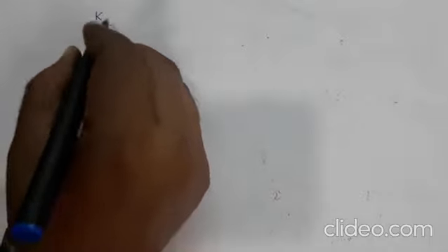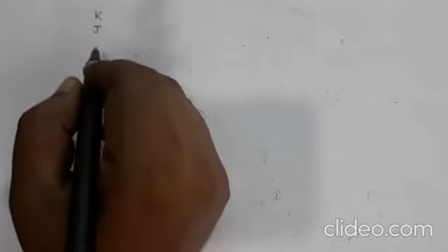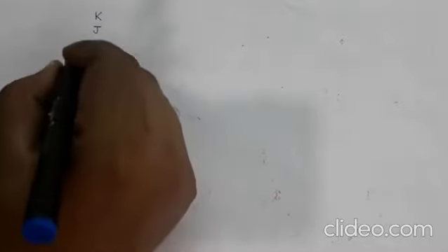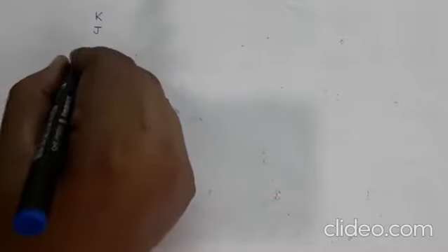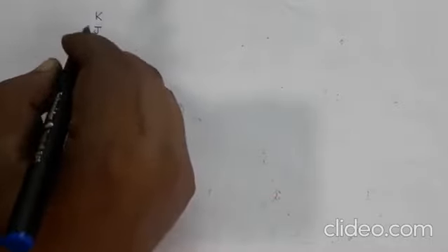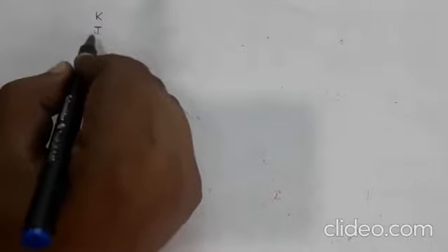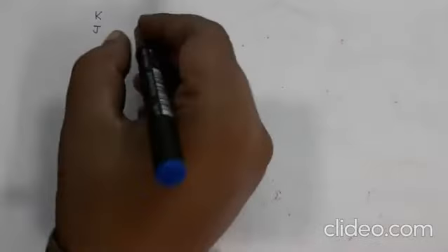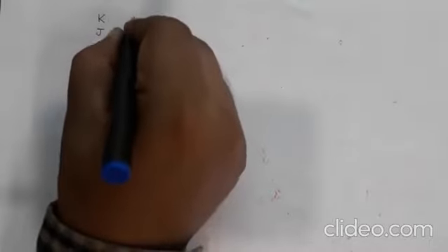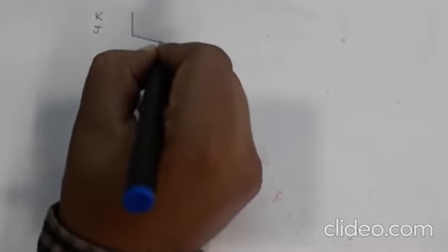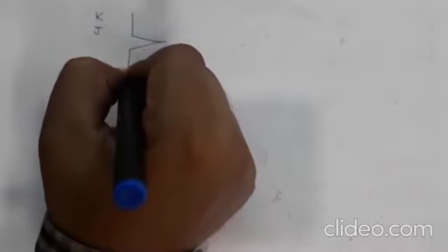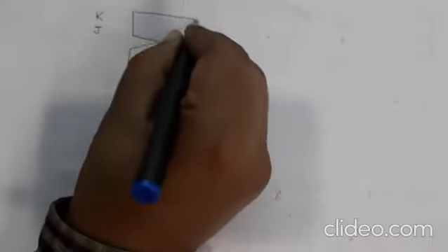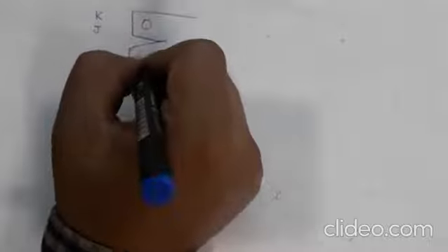These two formulations will not be valid for a blunt crack. You cannot have a hole as a crack in order to apply K and J. Although you can do it, the formula we have derived will not be applicable in that case. So we need a sharp crack in our CT specimen, compact tension specimen, before doing the test. Okay, right?